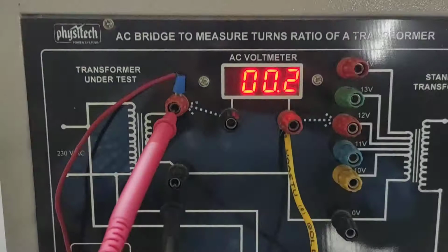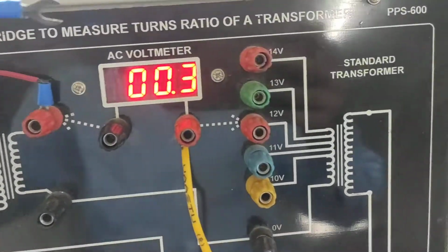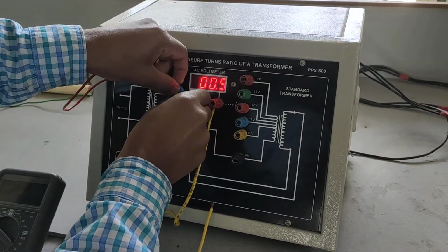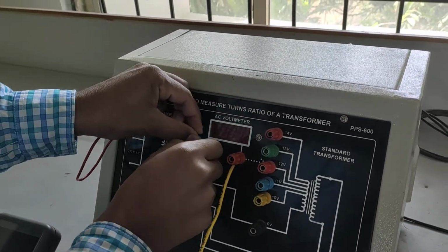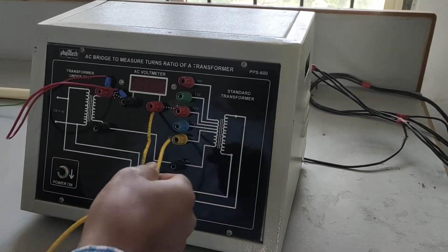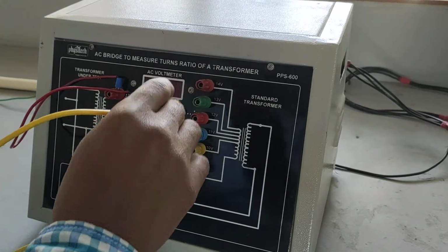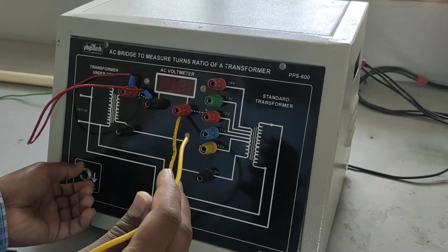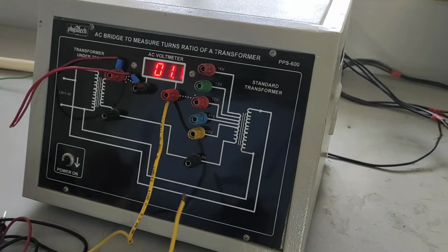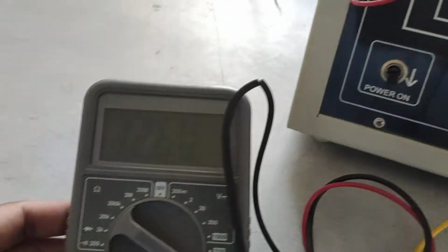Now here the connections are very simple, it is very easy. Here you can see these two. This is one terminal which is going to be connected to this. Because we need to provide some connections, here you can connect, and another terminal. Now we are going to vary the number of turns on the secondary side of this standard transformer. That's why I just connected here. I have taken this other end free to change the terminals. When you turn this on, you can find the tappings 0, 10, 11 volts, 13 volts, like that. If you check the voltage here, it's very simple. You can find this will be 12 volts. If you want, you can observe here, this is 12 volts.